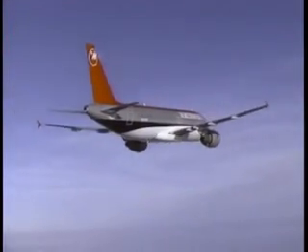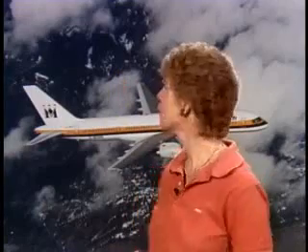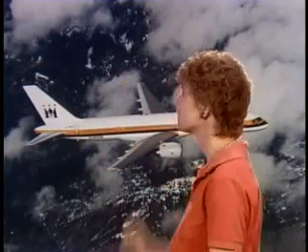Now, we've been talking about the outflow valve. Basically, what the outflow valve does, and it is located in the back of the pressurized aircraft, is control the cabin pressure on an aircraft. The way it does that is it gets rid of all the cabin pressure in excess of the amount for which it's set. So what you're doing is stuffing air in the front of the cabin, either by bleed air off the engines or through an independent cabin air compressor, and then this outflow valve in the back of the cabin will dump any air over the amount that you have called for in the pressurization controller.